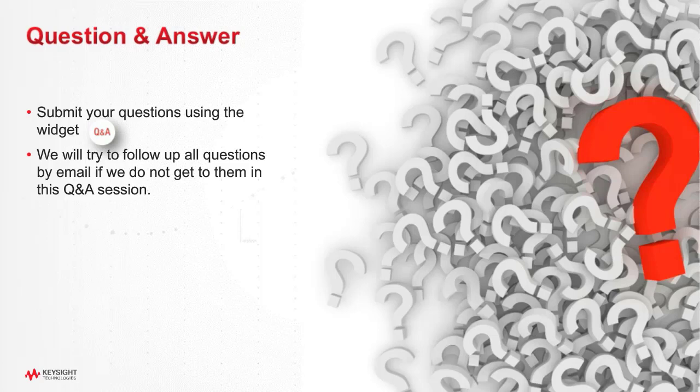A great question. Yeah, so in the presentation and the demonstration, I only showed us using an IBIS model. But in many cases, if you're working with particular CPU vendors, you might find that there's not an IBIS model that's provided, but you might get something like a HSpice netlist. So that's okay. ADS can work with the HSpice netlist. We will just create a transmitter or receiver block from that imported HSpice netlist, and then you could use that together with the DDR bus simulator.